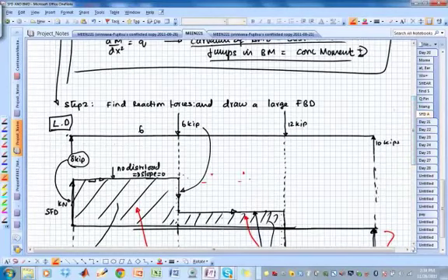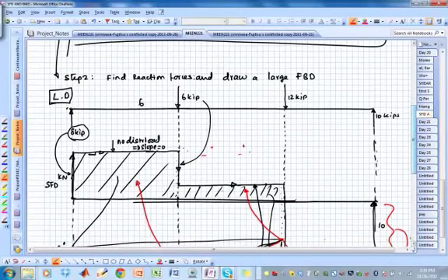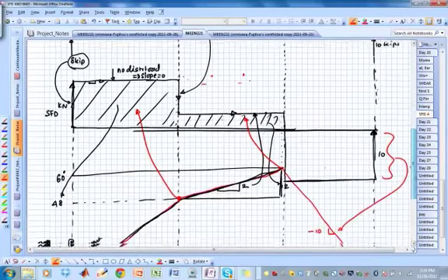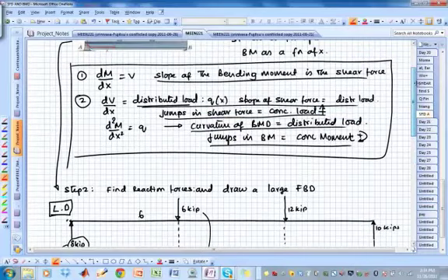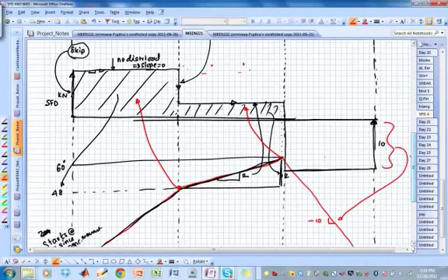So what we do is you first draw the load diagram, then jump up with the concentrated load. So if it goes up by 8, you go up by 8. If it goes down by 6, you go down by 6. By 12, up 10. And then use this to draw the bending moment. This actually enforces these three conditions. dM/dx equal to V, dV/dx equal to distributed load, jumps in shear force equal to concentrated load, jumps in bending moment equal to concentrated moment. Notice there is no jump in the bending moment at all because in this case there is no concentrated moment.